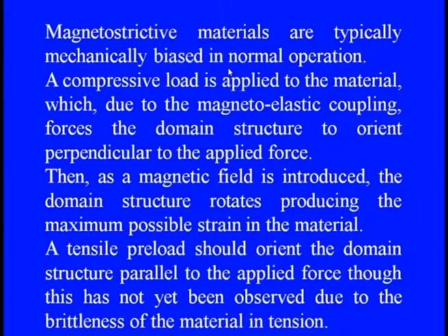So a magnetic field is introduced, and the domain structure rotates, producing the maximum possible strain in the material. A tensile preload would orient the domain parallel to the structure and the applied force, through which we cannot get the maximum strain.